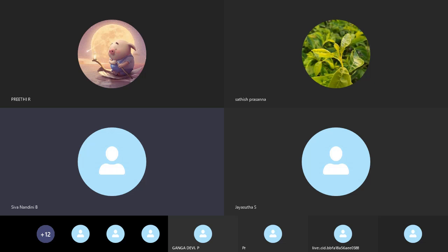So go to slide number 16. In slide number 16 we will see netlist generation. What do we mean by a netlist? It is a text document which contains ASCII characters. ASCII characters means alphabet characters, numerical characters and some symbols. This netlist contains information about the connection of electrical components. That is, how different electrical components, the resistor, capacitor, ICs, switches or batteries, are connected in the circuit diagram. All those connections are represented in a textual format in the netlist.